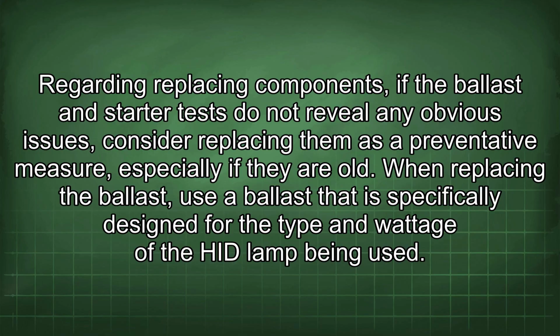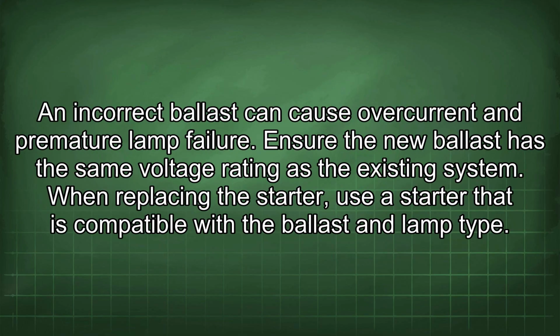When replacing the ballast, use a ballast that is specifically designed for the type and wattage of the HID lamp being used. An incorrect ballast can cause overcurrent and premature lamp failure. Ensure the new ballast has the same voltage rating as the existing system.